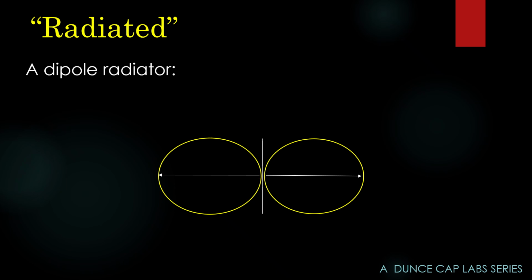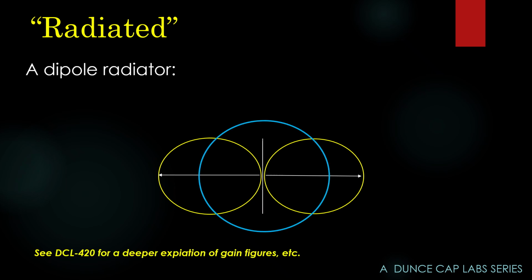Compare this to the isotropic model. It radiates in all directions. The dipole is actually radiating in a donut pattern. We've sliced the donut, so the dipole, if it's hung vertically, is radiating in all directions, north, south, east, and west, toward the horizon. But what the dipole is really doing, it's not wasting all this energy that the isotropic throws up here and down here, and it throws it, focusing it on the horizon.